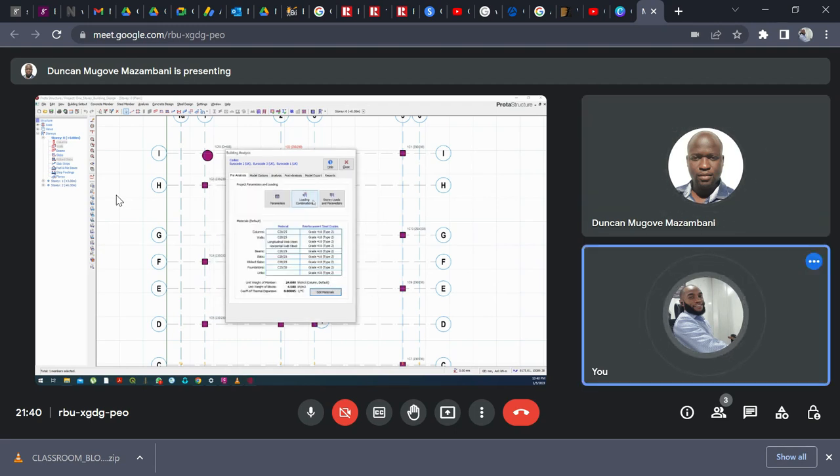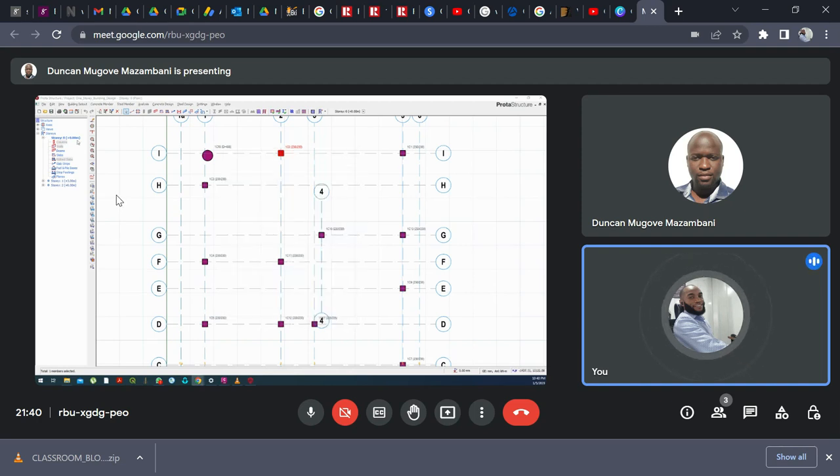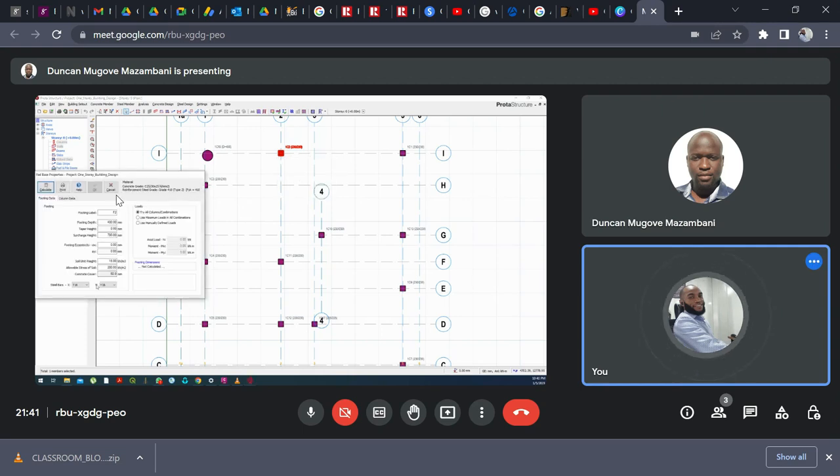then close. Then try to save this, just click on save there. Okay, then go back to the place again and do the same thing, click and say insert footing. Okay, that's fine. Then input your values back, put in your footing depth of 300. Let's start from there. Then put in your bearing capacity, let's use 150.